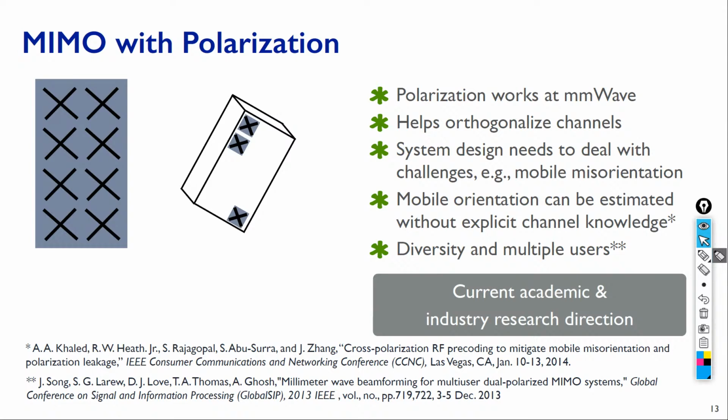You don't get any induced current. You cannot detect or receive your data successfully. To avoid this case, we use two polarizations, so that if one of the polarizations, let's say vertical, was reflected wrongly and is not aligned with the receiver, the other will compensate for that, and the other will be aligned with the polarization of the electromagnetic field at the receiver.